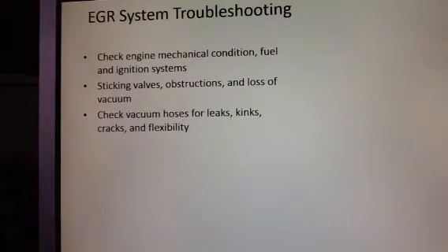Sticking valves, obstructions, loss of vacuum. And we need to be able to look at each one of these little pieces. Now the obstructions is one thing that we had talked about. With obstructions, we may not be able to see that without removing the actual EGR valve itself. We've talked about some of these where maybe some condensation mixing up with the carbon that's flowing through this, we can create a gummed up kind of instance in some of these intake manifolds.